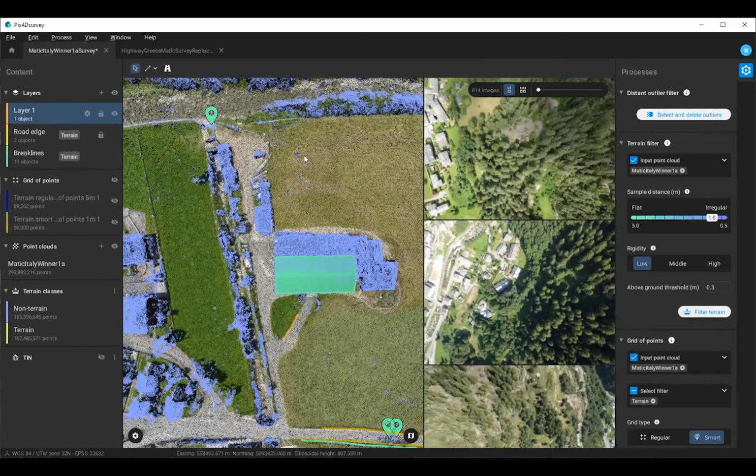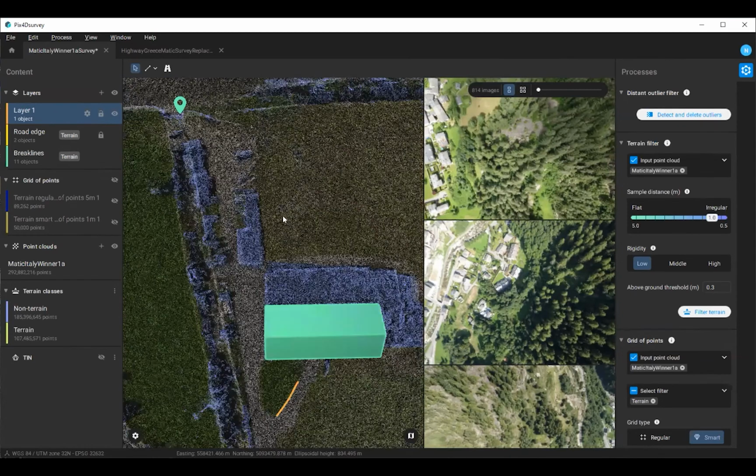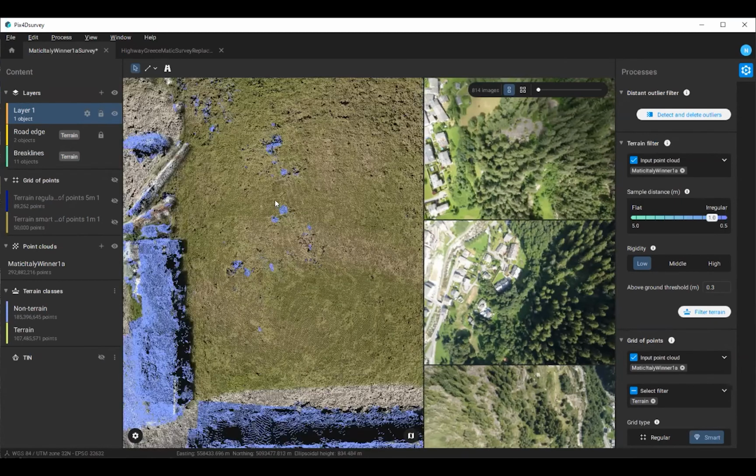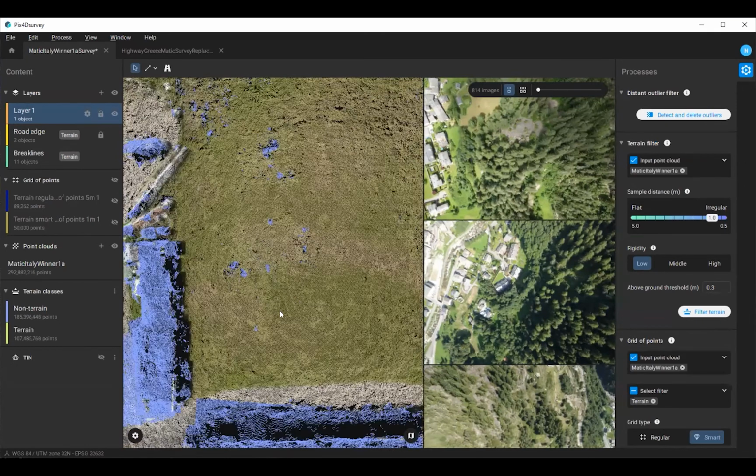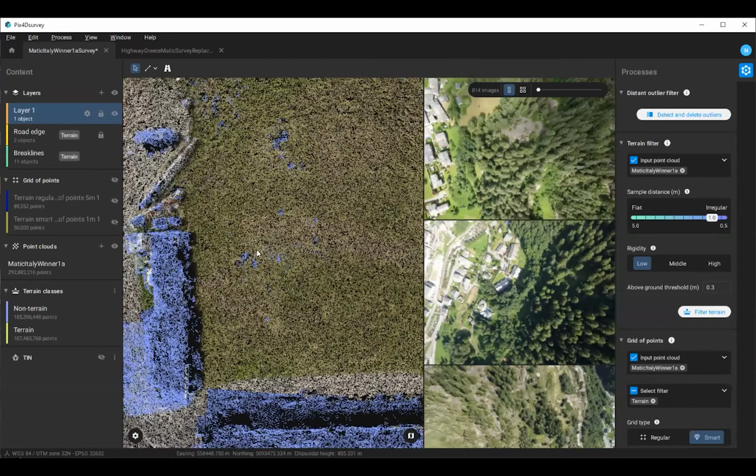And we also have a few simple little tools. Like in here, I can see there's some stuff that looks like it probably should be terrain, but wasn't. So if you are in the newest version of Survey that was just released yesterday, preview 1.7, just Control, mouse click, you can pick and then assign it to terrain in this case. And then if we take a look, yep, that was just grass. It wasn't classified right.